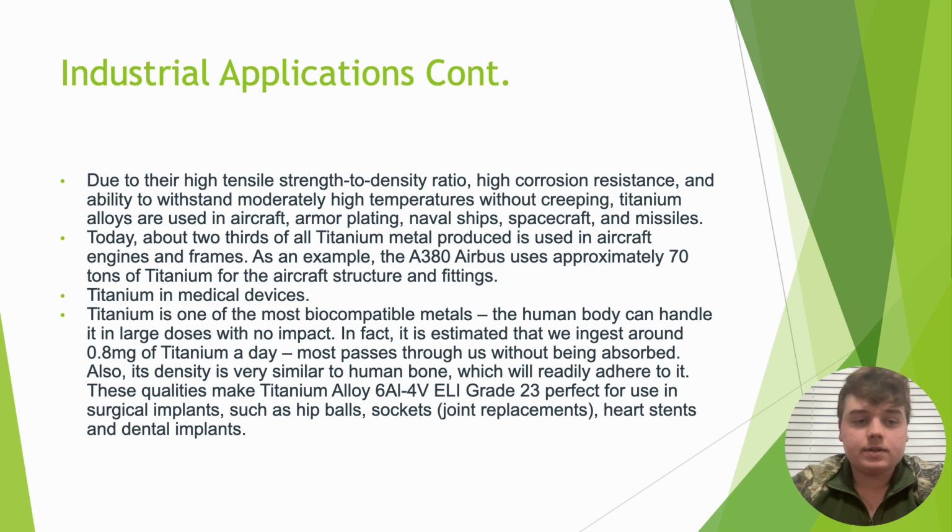Titanium in medical devices. Titanium is one of the most biocompatible metals the human body can handle. The human body can handle it in large doses with no impact. In fact, it is estimated that we ingest around 0.8 milligrams of titanium a day. Most passes through us without being absorbed. Also, its density is very similar to human bone, which will readily adhere to it. These qualities make titanium alloy perfect for use in surgical implants such as hip balls, sockets, heart stents, and dental implants.